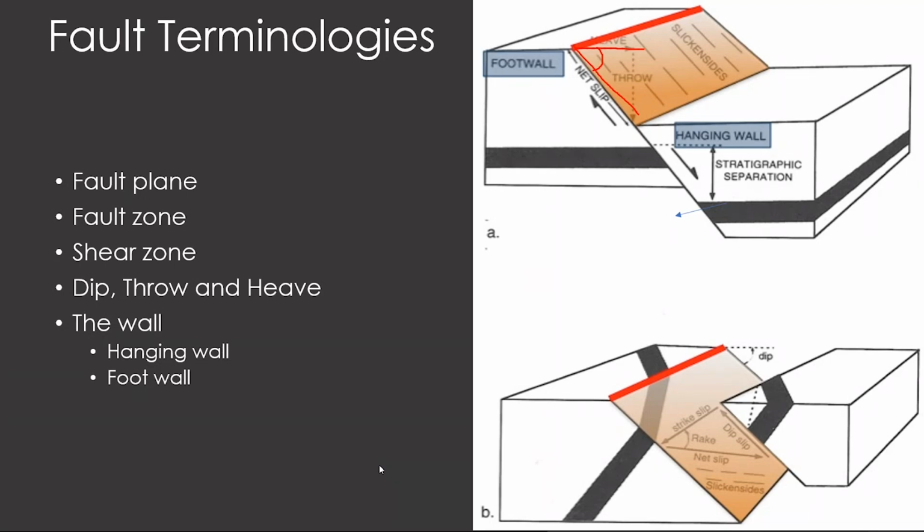In the previous case, when we studied the structure in the starting exposures, where we discussed the dip of a strata, that dip was the dip of the bedding plane. Here it is again a planar feature. What is the planar feature? The planar feature is this fault plane, and this fault plane has an inclination. So that inclination measured from a horizontal imaginary plane, we call it a dip. In both cases the concept is the same.